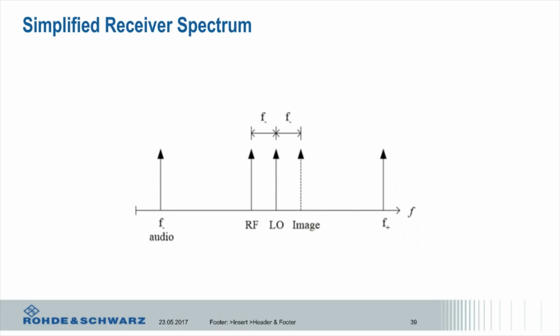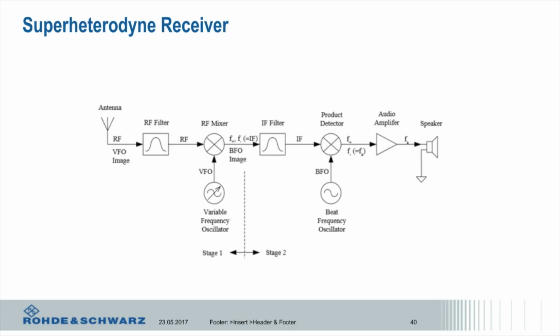But in the real world, there's going to be more complexity to these things. So if you look at it, there's that same sort of stuff on the left, but now I have an RF filter added to it. That's to first off limit the bandwidth of my spectrum so I know what the noise bandwidth I'm working in.